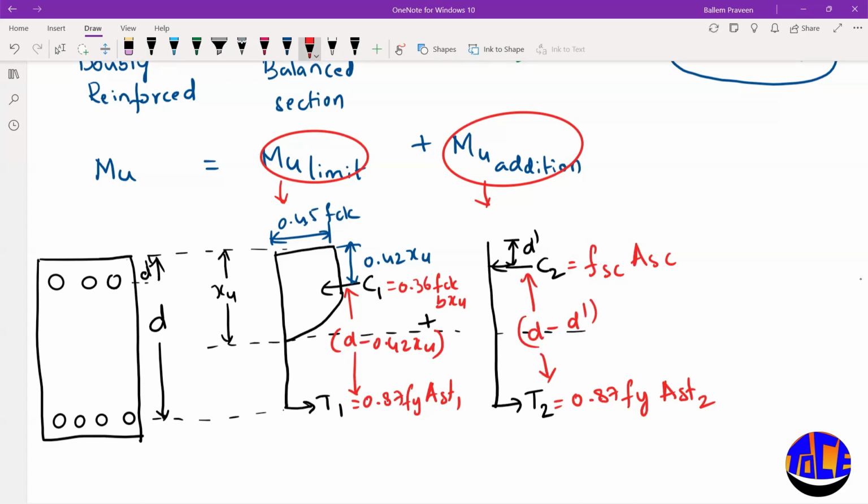Right? So what do you have to calculate, or design, in a doubly reinforced beam section? In a doubly reinforced section, as I told you, the depth is restricted, and you will be knowing the overall depth and width, as well as the grade of concrete, that is fck, and the grade of steel you are providing. So all these elements you will know already, and even the span of the beam and the supporting width, and the effective cover, everything you'll be knowing.